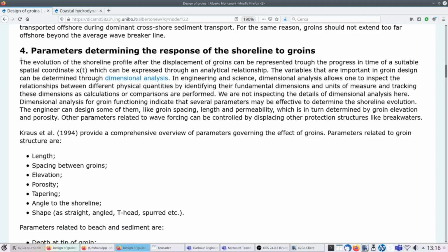Keep in mind the exercise that we just did, because this is, I think, an excellent input to understand the concept. So we understood what are the characteristics of along-shore sediment transport. We understood what the dominant parameters are, wave height, wave angle, and we understood how the along-shore sediment transport models the coastline, models the beach.